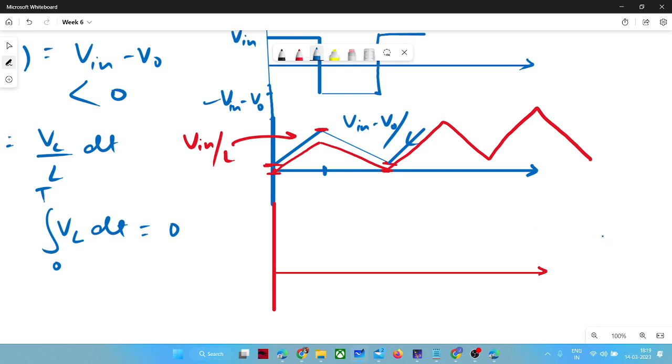If it is freewheeling through a non-ideal diode, then also the current will become zero, because you see the inductor as an energy source, and a non-ideal diode will have some voltage drop across it, right? If some current flows across that non-ideal diode, it will dissipate or consume some energy, right? If it is an ideal diode only, it maintains its current. Yes, the current through the circuit will not be zero. Okay. Any other thing?